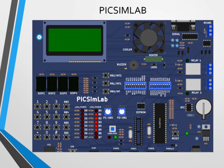PIC16F877A, it is a 40-pin IC and the size of microcontroller is equal to size of data bus, that is 8 bits, and it has 5 ports which are bidirectional: port A, port B, port C, port D, port E. Port A is of 6 bits, port B 8 bits, port C 8 bits, port D 8 bits, port E 3 bits. And these LED arrays, both the LED arrays, one is connected to port B and one is connected to port D.